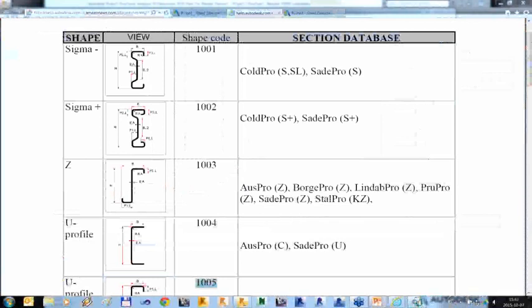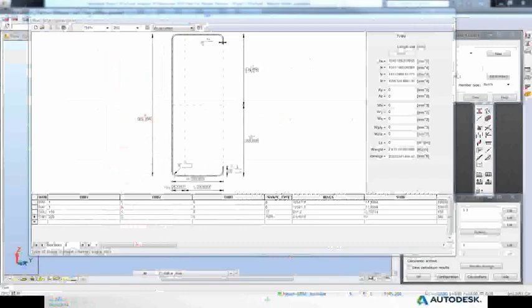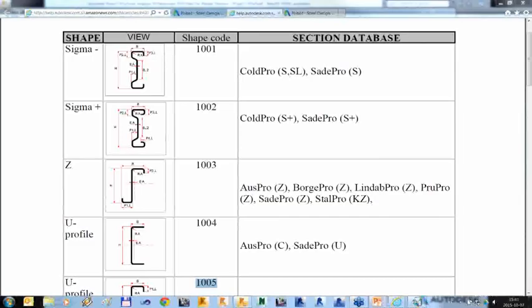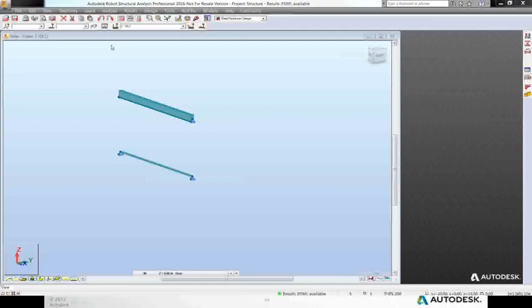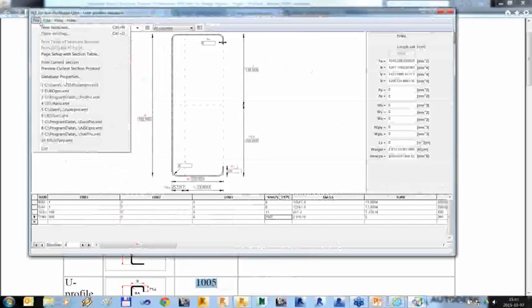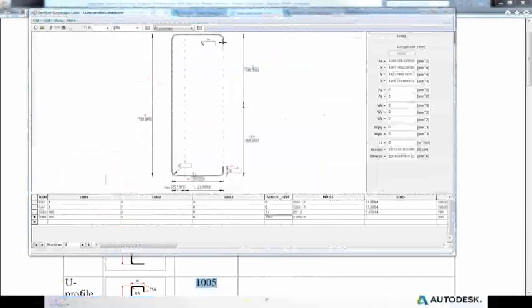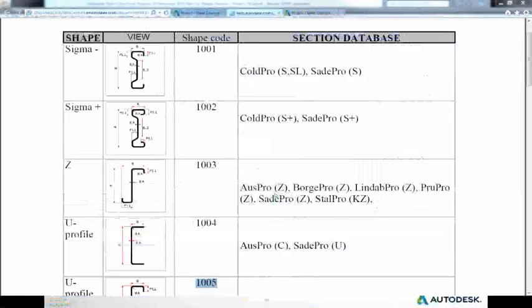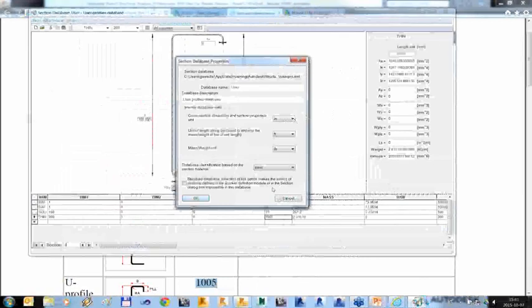So there was also a question whether it is possible to edit native or standard databases. Okay, the bottom line, it is not what we recommend. However, it is possible when you just uncheck the standard database mark, which is available in the properties of the database. But personally, I'd rather suggest that you copy this database, give it a new name or a new description, and then edit. Just in case you make any mistake, you may return to the original file.